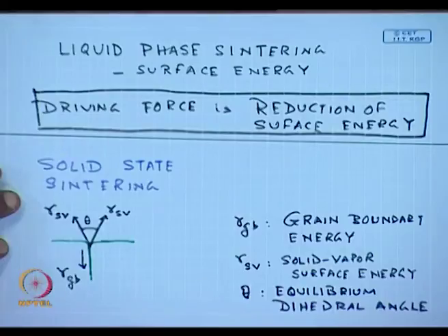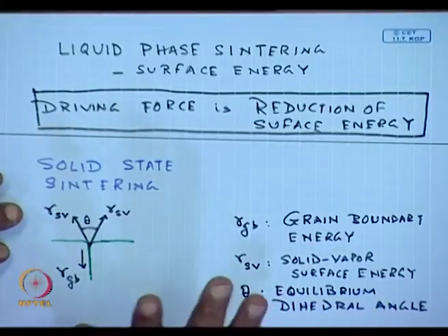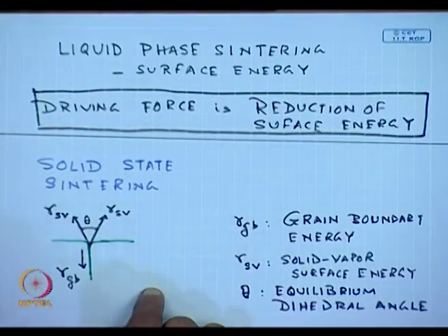In sintering, let us take solid phase sintering first, which I have drawn over here. The driving force is a reduction of surface energy. Smaller particles have high surface energy. So, if they agglomerate, what will happen? It will generate a larger particle, and surface energy will be reduced.